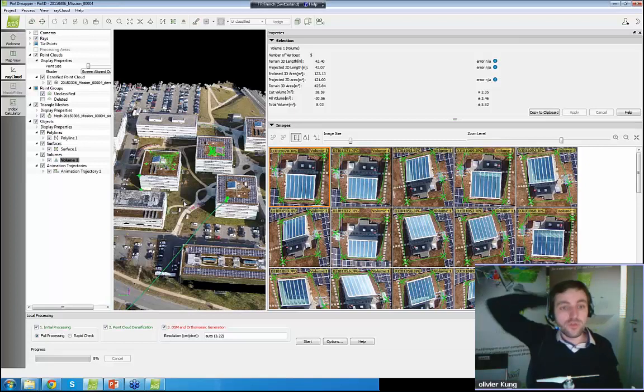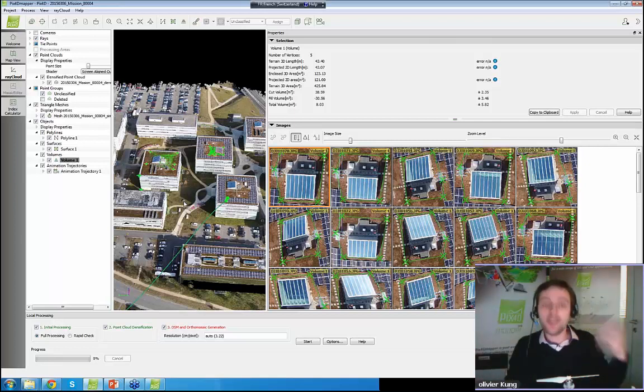So basically, when we allow the Pix4D Capture app to fly at a lower altitude, we will have to increase the image capture rate a lot, as well as decrease the speed of the drone. That's the reason why we didn't include altitude change from the start.